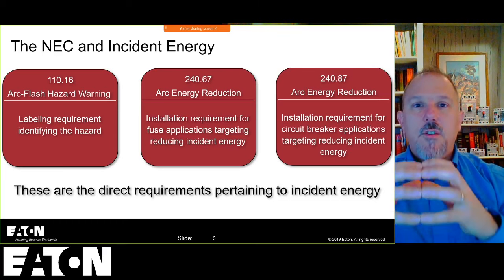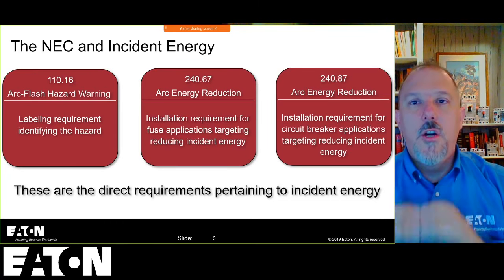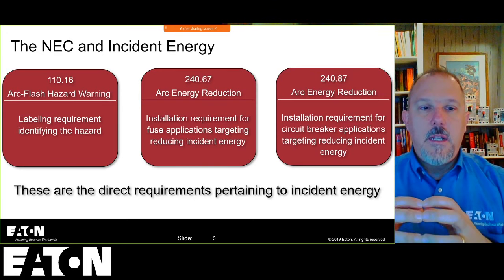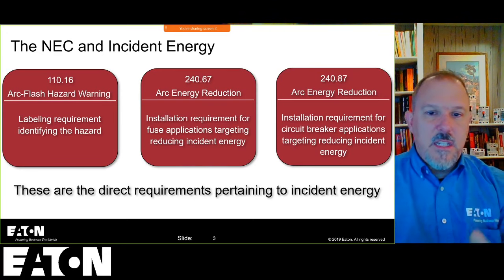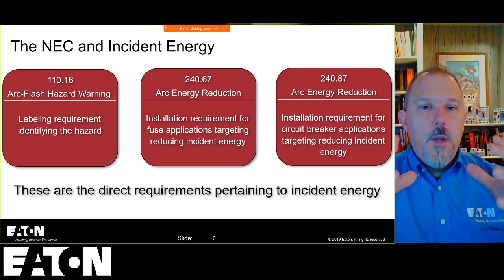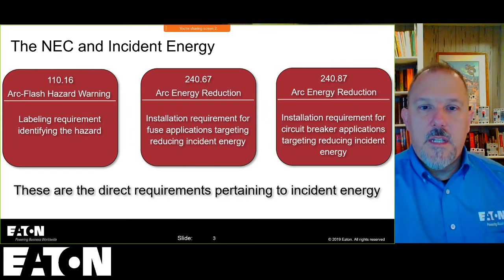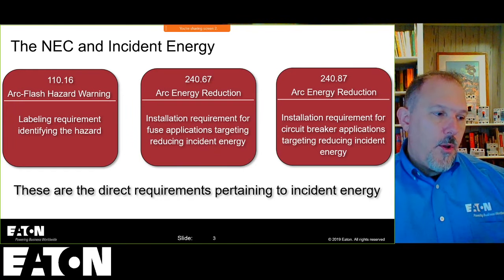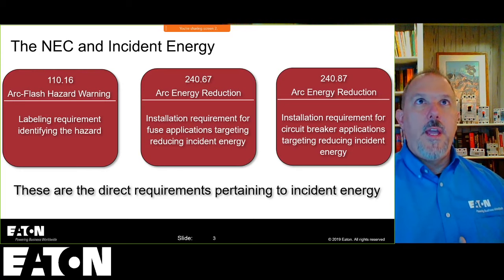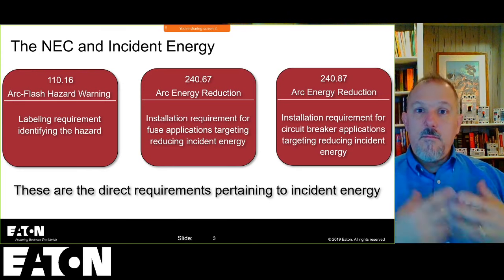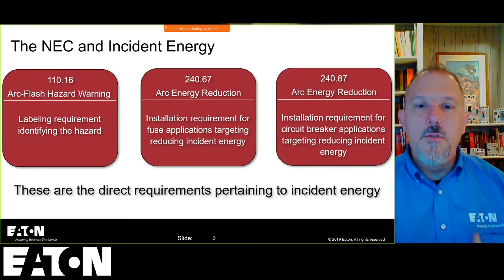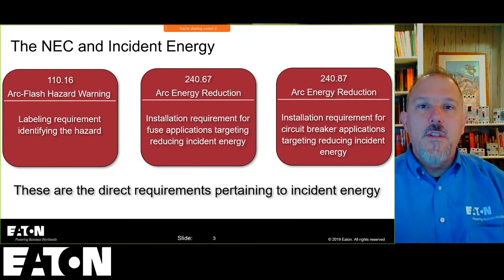You have to remember what was going on in the 50s, 60s, and 70s. We were going from ungrounded systems. Early in our electrical history, we had ungrounded delta systems. Why did we do delta systems? Well, the first ground fault is a give me, right?